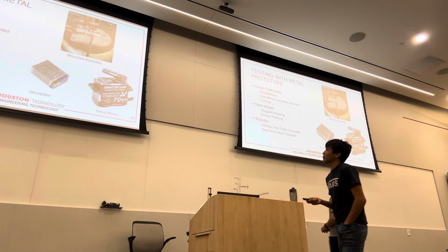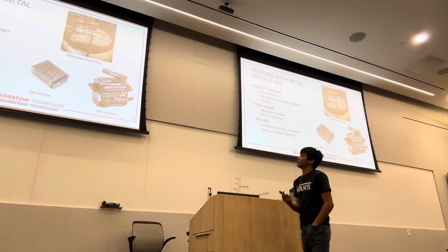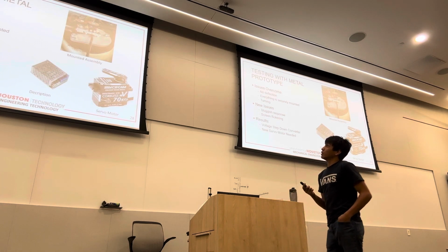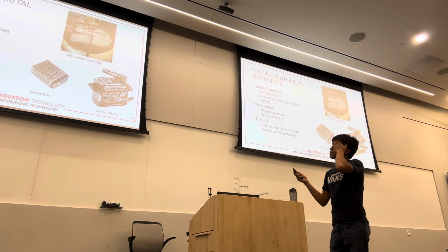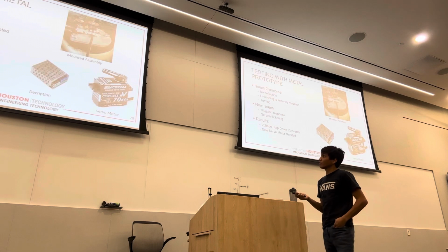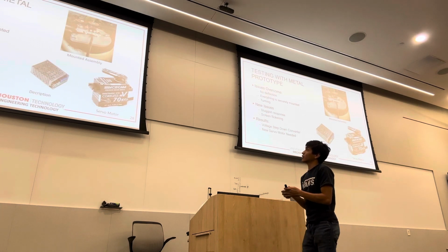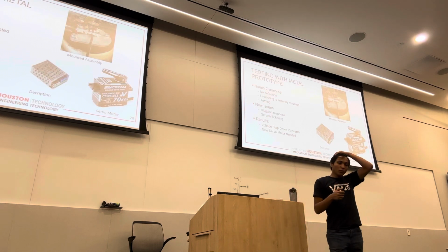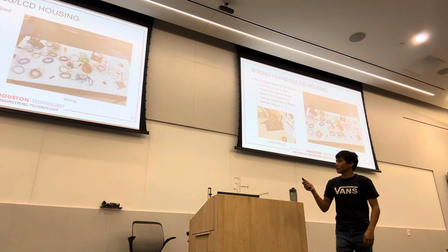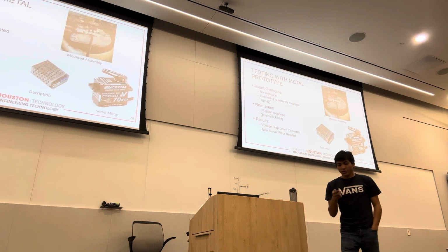Testing with the metal prototype. At this point, before, it was moving fairly sluggish, and we assumed it was because it was deflecting so much. Once we went to the metal, that did go away. Everything was securely mounted, it was turning, but it was still fairly sluggish, and the weirdest thing was the screen was flickering, and we couldn't figure out why. It was because we were basically maxing out the voltage. We were operating the servo at 5 volts, because that's what the Arduino puts out, and it needed to be operated at 7.4 volts.